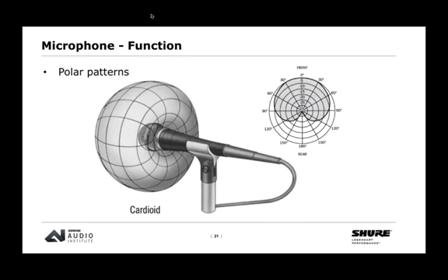So you could consider something like a cardioid style mic. And if you notice the graphic on the right-hand side there, we're showing its pickup pattern is directly in front of the microphone. And the further you get off axis to one side or the other, 90 degrees, it starts to become attenuated all the way around to the rear of the microphone, where there's the most attenuation at its 180 degrees off axis position. In a perfect world, you would point this thing towards the talker and the noisemaker, whatever that might be, the HVAC or the projector fan noise, would wind up in the null or in that 180 degree section of the microphone.